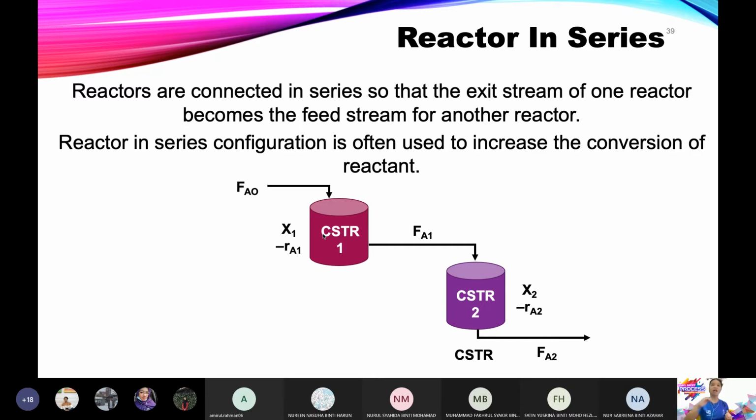Why does conversion increase? If you remember, conversion is how much has reacted over how much I fed. How much reacted over how much I fed. So naturally, with more reactors, more A will react. So conversion will increase with the number of reactors.